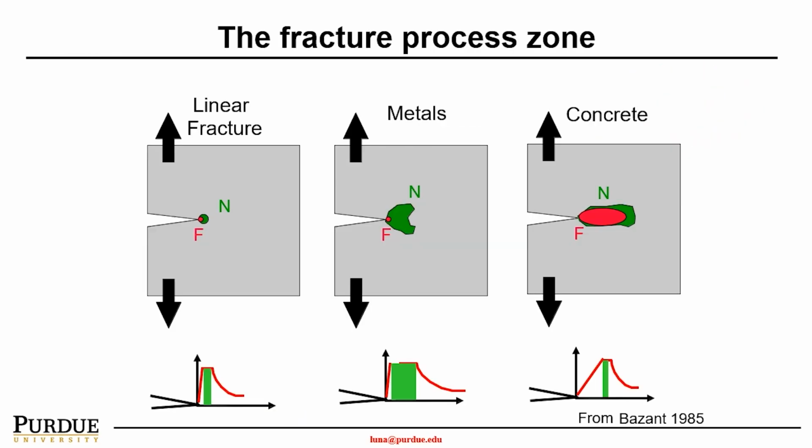So linear elastic fracture mechanics works really well in the field of brittle materials or ductile materials such as steel. However, it doesn't find very relevant to quasi-brittle materials such as concrete. For instance, in linear elastic fracture mechanics, you consider there is an existing crack, and then there is non-cracked surface.